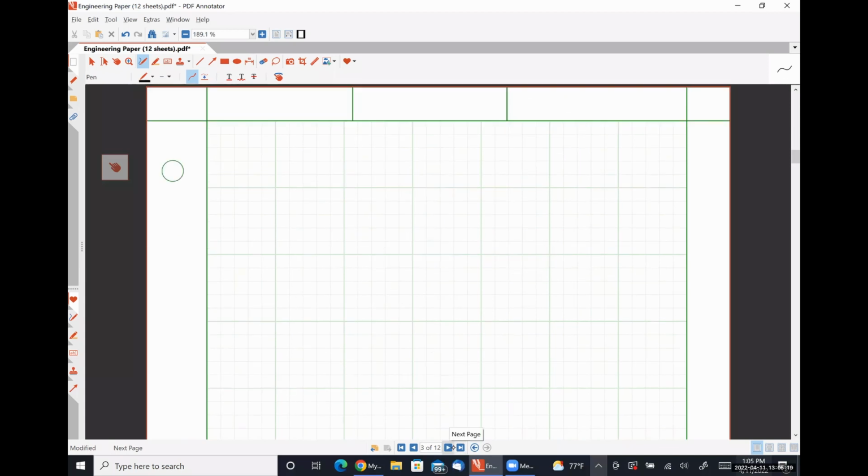So we are now going to actually get into the frequency response of some of our amplifier circuits that we have analyzed. I am going to work specifically with MOSFET amplifiers, but the techniques that I'm showing you can be absolutely applied to BJT amplifiers as well. The principal difference there is that we're going to find that the Thevenin voltage and the Thevenin resistance equation are going to be slightly different because we have to include the contribution of r pi. But other than that, the derivations should be literally identical.